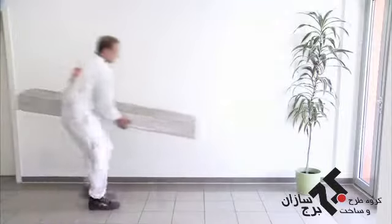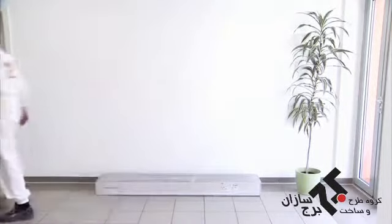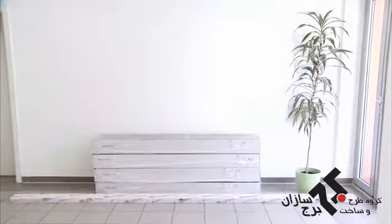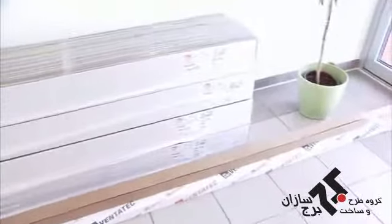A perfect ceiling is the crowning glory of every room. In order to achieve an outstanding result, you should ensure that the ceiling components are kept clean and dry during transport and storage. The underlying surface should be flat and level to avoid damage. The E.M.F. tiles may only be installed once all plaster and screed works are completed.